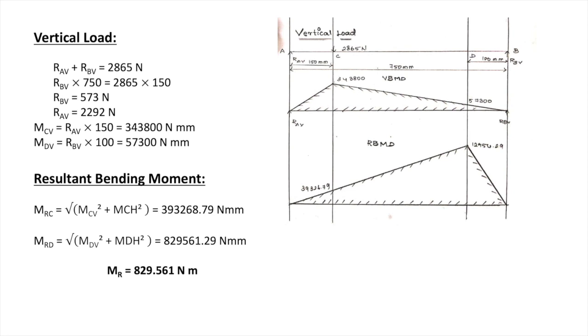And similarly for the pinion, here we could see that the moment at the pinion is higher, so we take the greater value obviously, so that the shaft never fails. In the design we'll always take the maximum value so that the shaft never fails, and only then will it be considered a safe design.